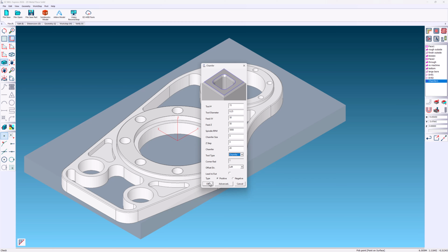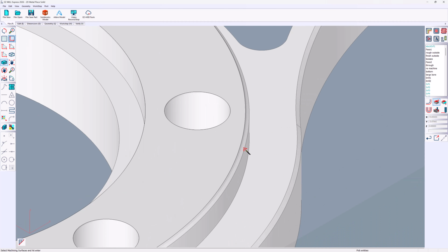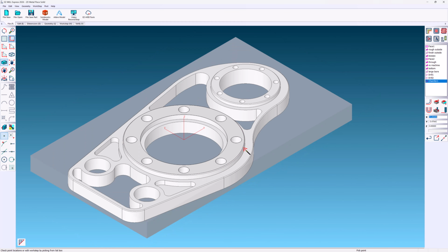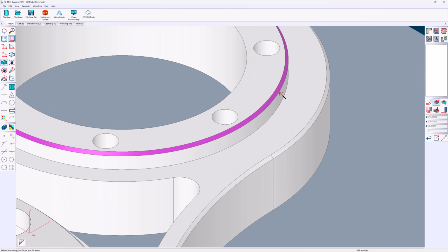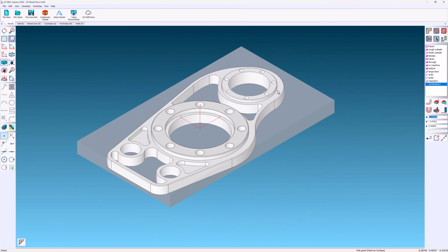Smart Click is activated for chamfers using the button just above our simulation icon. Because all the information for our other chamfers is the same, I'll duplicate the operation and swap out the faces. To remove the prior face selection, simply click outside the part and all the faces are removed for you to select new ones. Duplicate as many times as needed.